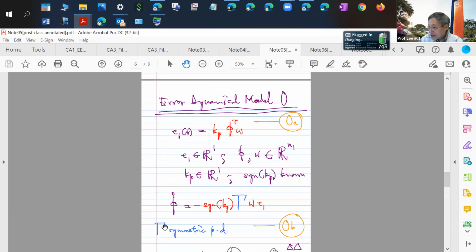And the stability analysis coming out of it guarantees you tracking error will go to 0 when you pair it with the adaptation like that. But still, you cannot say anything about convergence of even the parameter error. What is nice about this simpler one is, as I told you last week, at least you can begin to see that out of the stability analysis, because I integrated the square of the tracking error, I look at boundedness of the signals.